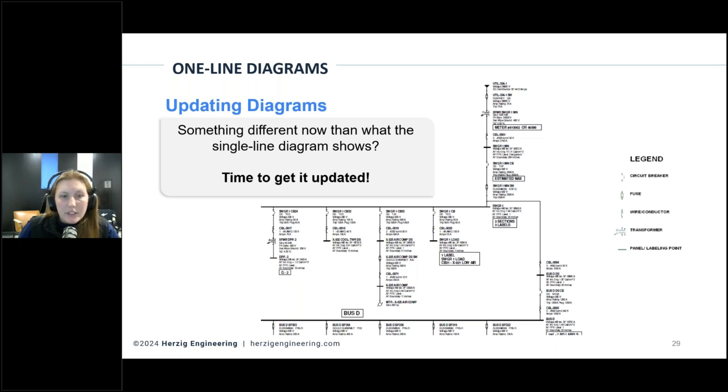Yes, 3-phase circuits are typically what we're concerned about. By and large, single phase, I mean, it can arc, it can flash on you. I'm not going to say it's not hazardous, but there are no specific calculations for that. And it's been suggested that you use 3-phase calculations for single phase to be conservative. But there's been some research that kind of justifies that it might be over conservative. So yeah, we're typically worried about 3-phase.